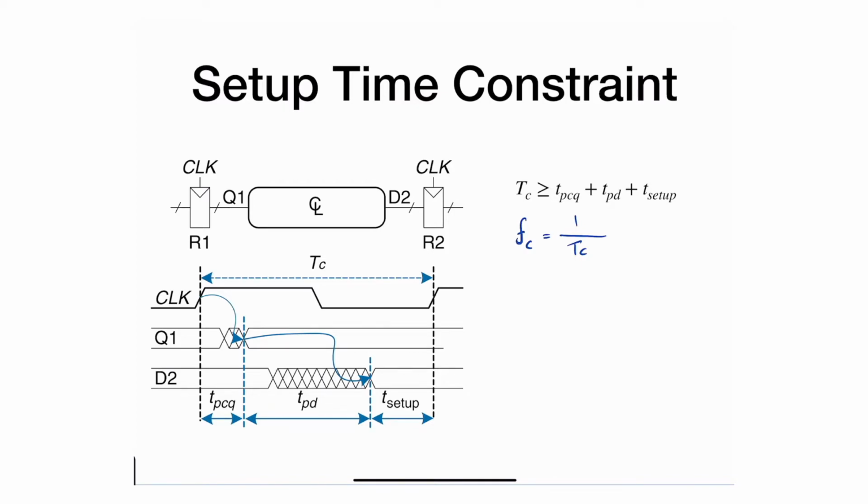Anyhow, let's discuss a little bit more about this circuit in here. Usually, the propagation clock to Q depends on this particular flip-flop, and I'm assuming we're using the same type of flip-flops. So, as a designer, you usually don't have any control over it. You look at the data sheet, and that's what you get. The same goes with the T setup. The setup time is also out of your control. So that leaves you a couple of things: either the propagation delay or the frequency.